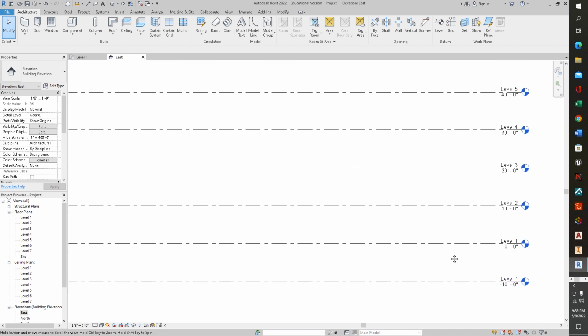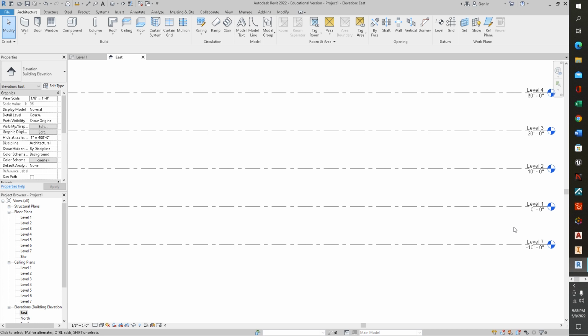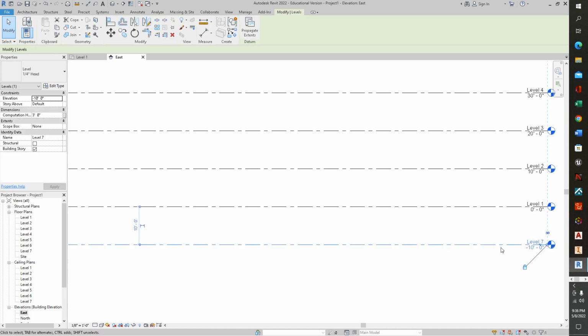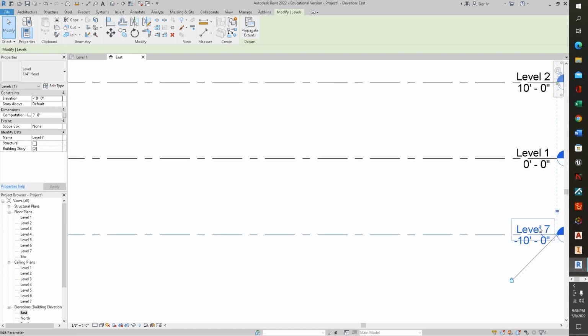We can actually adjust a lot of things with Revit. I'll start off with these level lines. You can change the label on them by simply clicking on the level, and then as it's highlighting the box around whatever it is that you're trying to change the label of, you can actually open that up to edit it. So we'll actually go in and tell this it is foundation level. And we'll press enter.